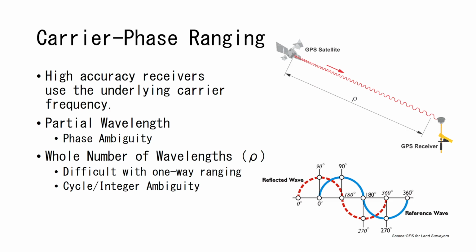We call that the cycle ambiguity, or the integer ambiguity, and that's the difficult one. The nice thing is there are a lot of methods out there to help us determine that. And as long as we're locked onto a satellite and constantly receiving a signal from it, that length is going to be typically consistent, which helps us a lot to be able to calculate this.